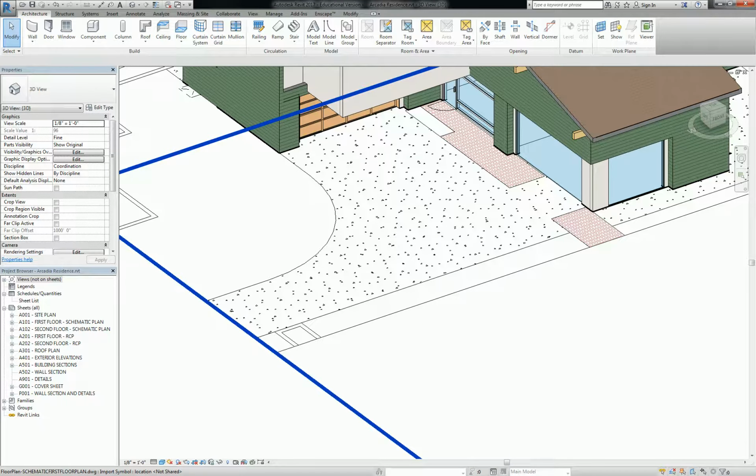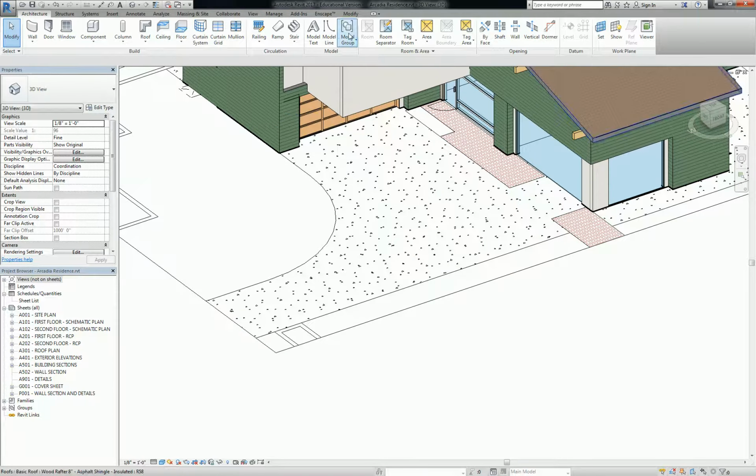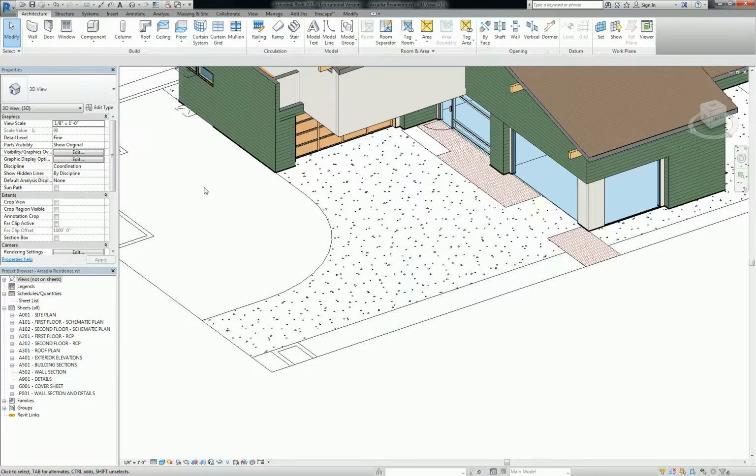Diagrammatically, our curb cut, that's a terrible marker, but our curb cut is going to have a shape that looks like that, right? And this is the driveway. And this line and this line, everything here is sloping down straight, and then everything here is sloping down to that point. So what we need to do is define the height of this point and that point on both sides. You do that by modifying parts of the surface that you have modeled. If we simplify this and it's mostly flat, we can just do a floor family.